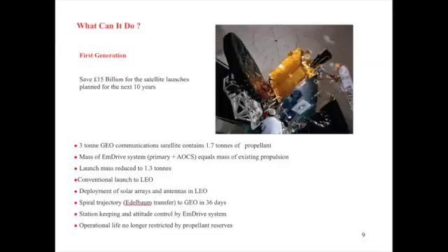In terms of real measurements, you're getting rid of about 1.7 tons of mass from a classic 3-ton satellite. So you reduce the launch mass to 1.3 tons, therefore you use a smaller launch vehicle, or alternatively you can put more satellites on the same launch vehicle. You essentially launch it to low Earth orbit instead of its transfer orbit.